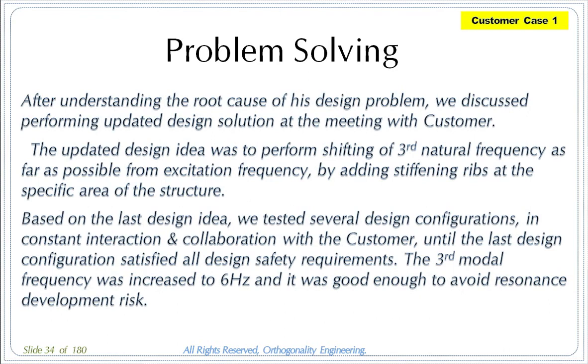Problem solving. After understanding the root cause of his design problem, we discussed an updated design solution at a meeting with the customer. The updated design idea was to shift the third natural frequency as far as possible from the excitation frequency, by adding stiffening ribs at a specific area of the structure.